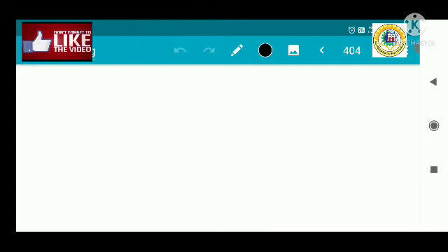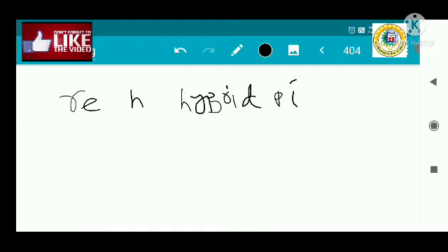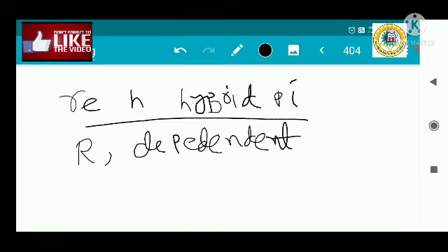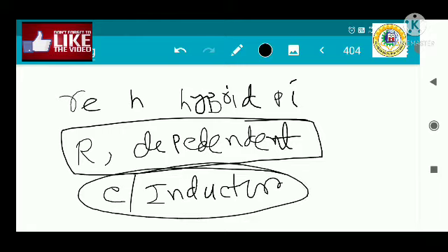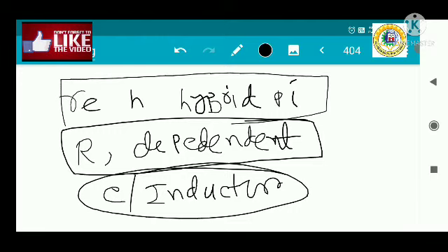Next we discuss some of the capacitances. We will study what factors are responsible. In the case of the AC circuit, whenever we model the transistor with the help of the re model, h-parameter model, or the hybrid pi model, we only consider the resistances and dependent sources to model the transistor. So we have not used any capacitor or inductor in our circuit to model the transistor. Okay, that is the disadvantage of this model.